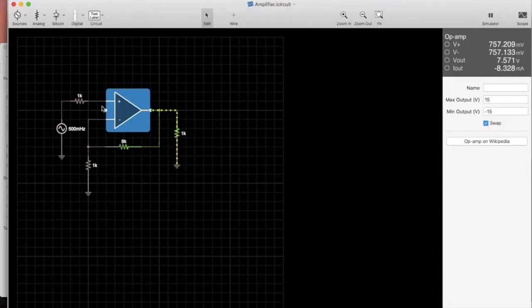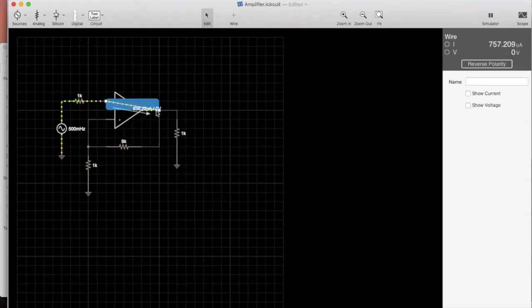And you can see up in the top right window all the parameters for the op-amp. So we've got 1 millivolt in, or I mean 1,000 millivolts in, which is a volt, and you've got up to 10 volts out. So 1 to 10 gives you a gain of 10, which is what this is producing. And we've got the negative feedback loop down here.